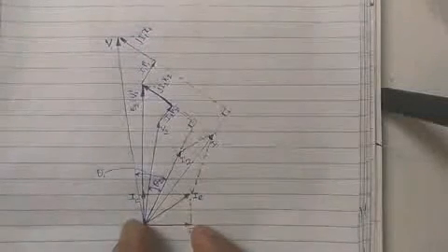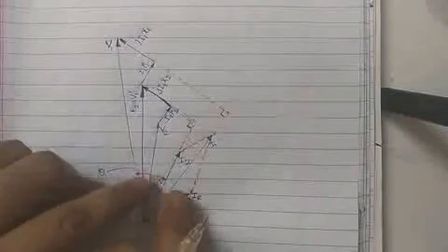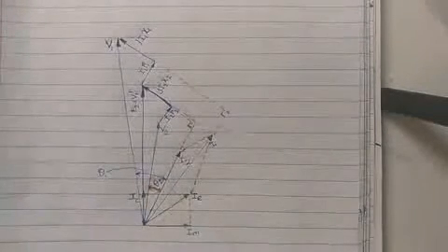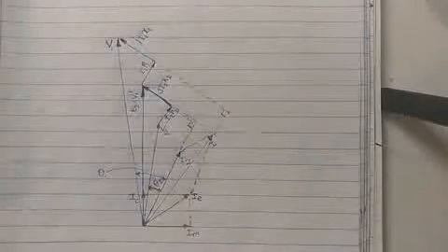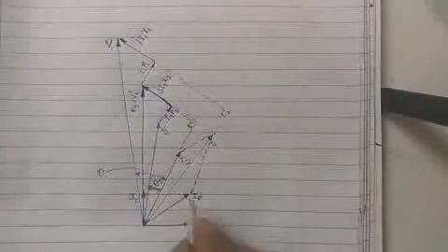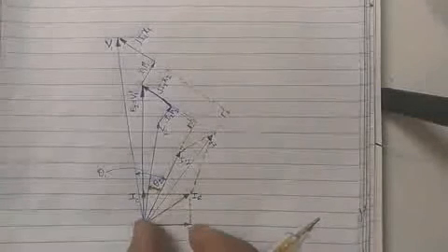Now for the equivalent circuit in general form, first we have to draw the phasor diagram. Here I2 is taken as the reference. First you have to draw the secondary side voltage and secondary side current. Suppose the current lags the secondary voltage by an angle theta 2, as we are working with an inductive load. Now the exciting current has two components. One is the magnetizing component current Im, and another is the core component current Ic, which should be in phase with V1 dash, that is equal to E2.